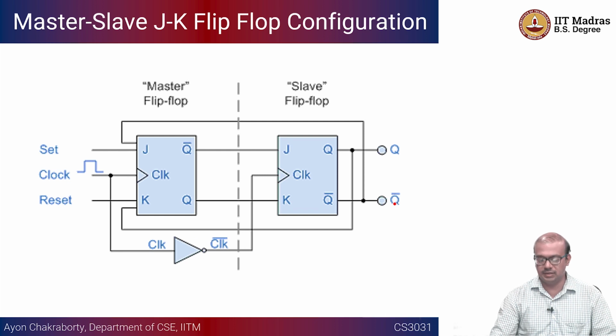And this removes the problem of the forbidden state that RS latches used to have. And then we saw that D latches were level triggered, we made it edge triggered by introducing one more flip-flop, and then we looked at the JK flip-flop, which is basically having one more extra feedback, right?